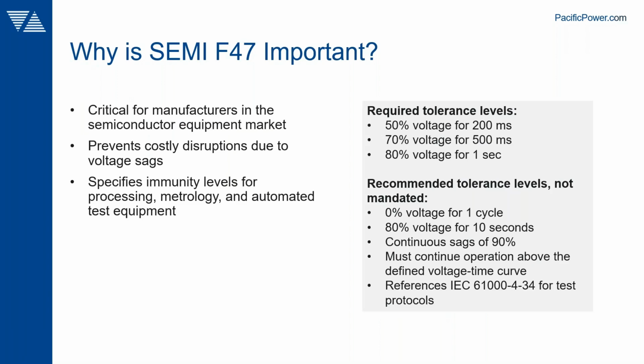That generally means more hold-up capacitance in the input stages than you would normally use in equipment like this. So there are ways to make this work by designing for it, but even then you still have to validate, verify, and test. This is often done by test labs that can run these tests for you, and a lot of developers will want to do their own pre-tests in-house before they go to a TUV or a test lab like NEMCO, because they're expensive, they charge you by the hour, and it can take a lot of time if you fail during a test and have to go back later.